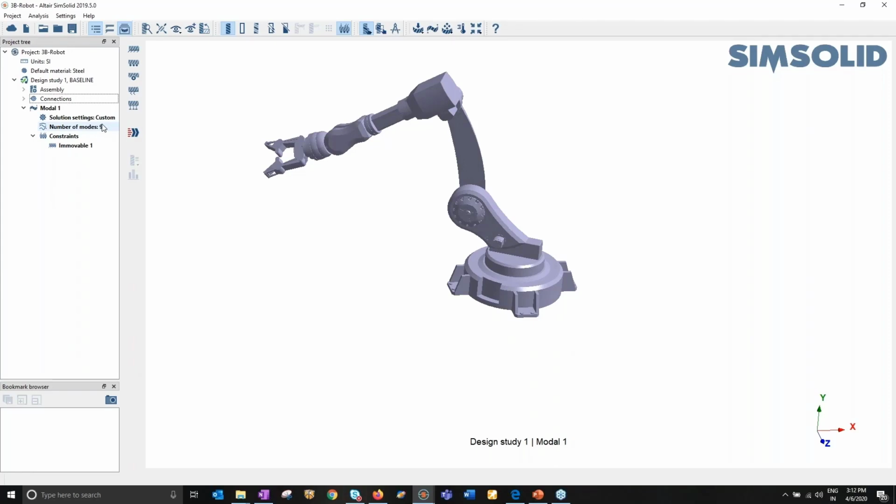Also, modal analysis is very important for many reasons, as you know. One among them is, of course, to identify the frequencies or modes of the parts. There are many other derived applications of modal analysis as well. For example, checking the connections of a large assembly. So whether your assembly is properly connected or not, or whether your assembly is properly constrained or not. All those things you can very easily check with modal analysis.